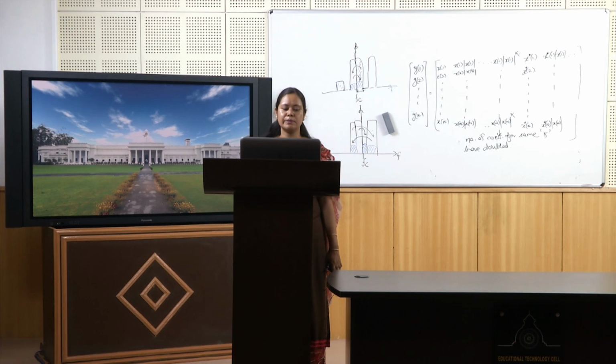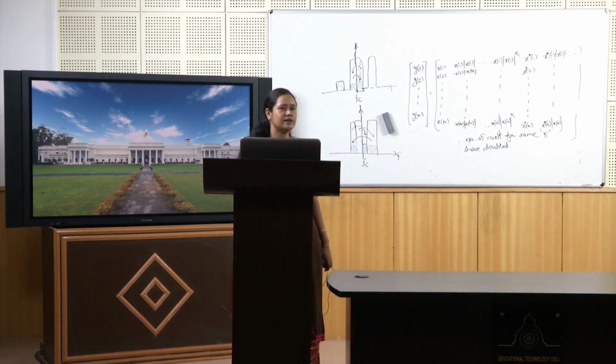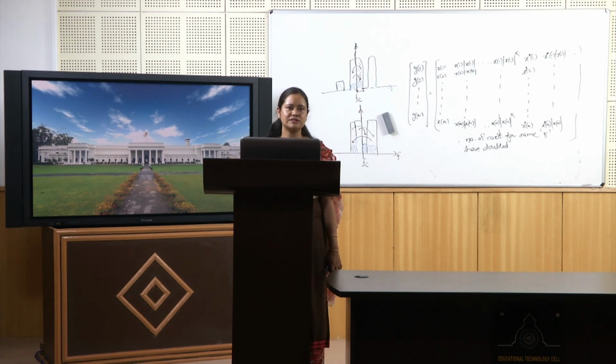It is reconfigurable in nature. It means if our power amplifier changes or our IQ imbalance property changes, then we can tune our coefficients easily, and we do not have to change anything hardware wise. So, it is a great advantage, because in analog circuits you have to change the whole circuit if anything changes